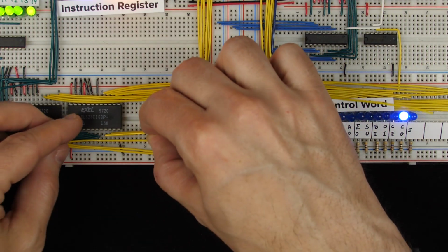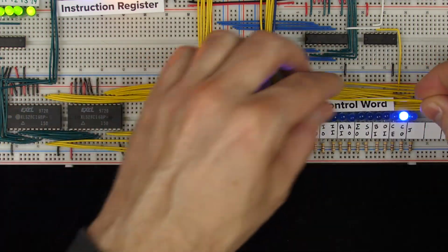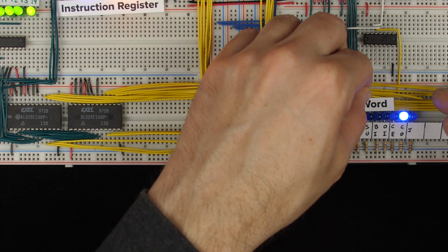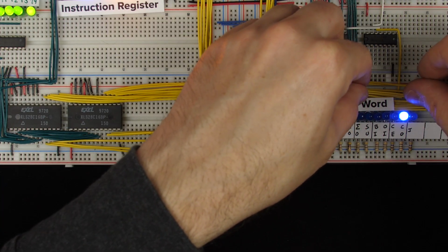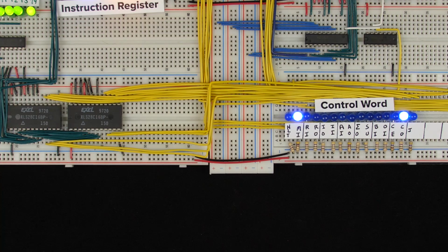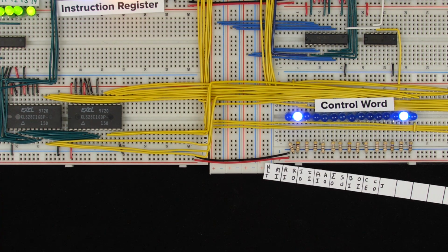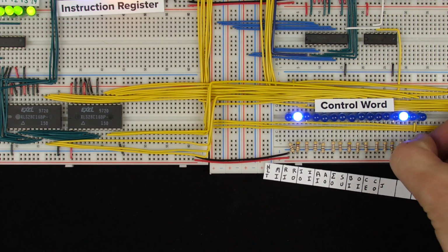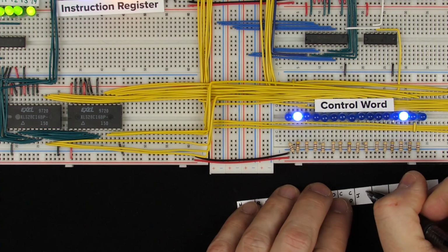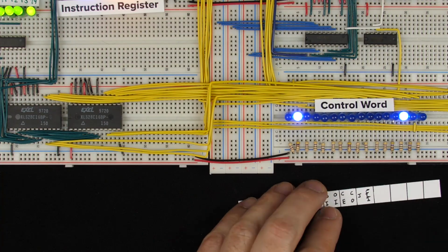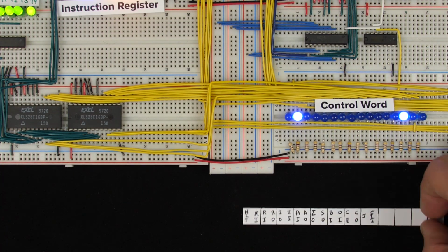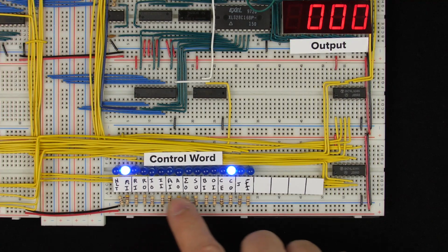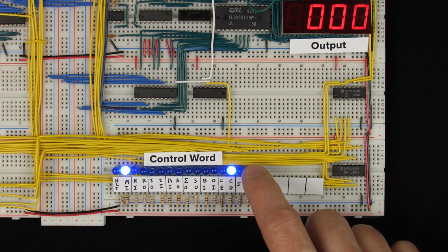So I'll connect that bit over to the control word and add a 16th LED so we can see what this last control bit is doing, just like the rest of them. Now I know a few people suggested using this unused bit to reset the microinstruction counter at the end of shorter instructions, which I think is a great optimization, but I didn't do that because I was planning to use it for this. And I'll also add a current limiting resistor to ground here, since otherwise the output of the EPROM will drive too much current through the LED. And then I'll update the label for this new signal as FI for flags register in. So there we go. And now all of these bits in the control word are active high signals.